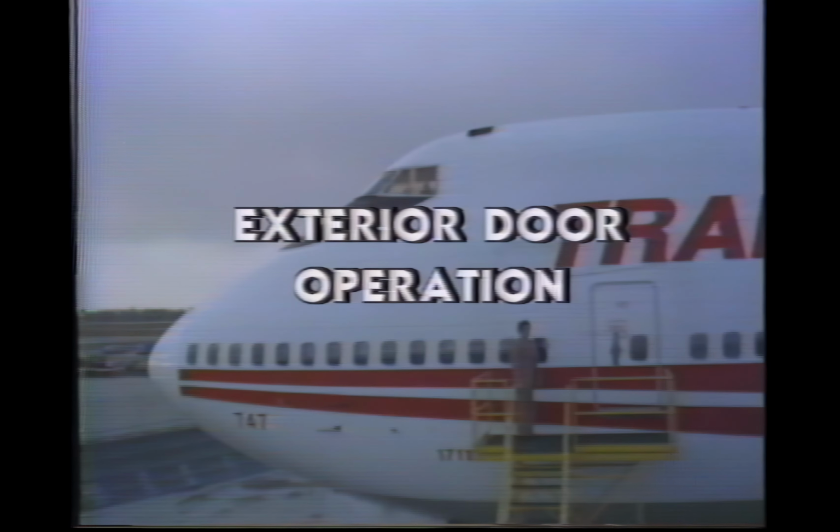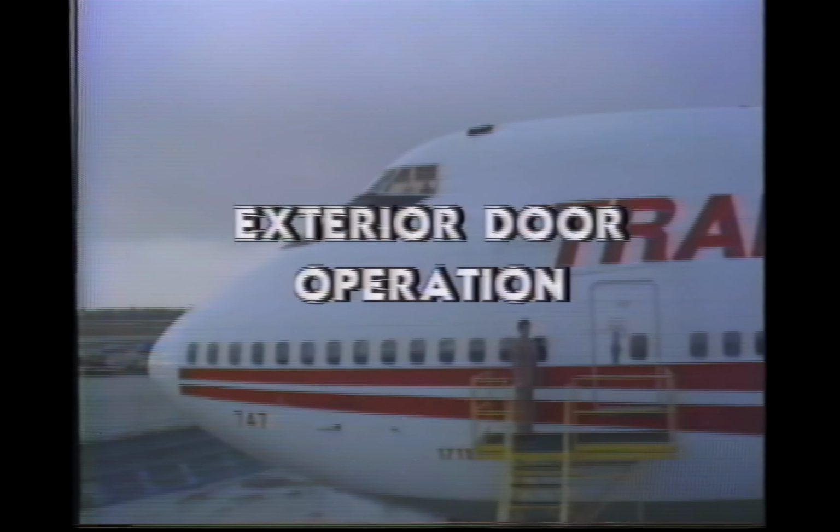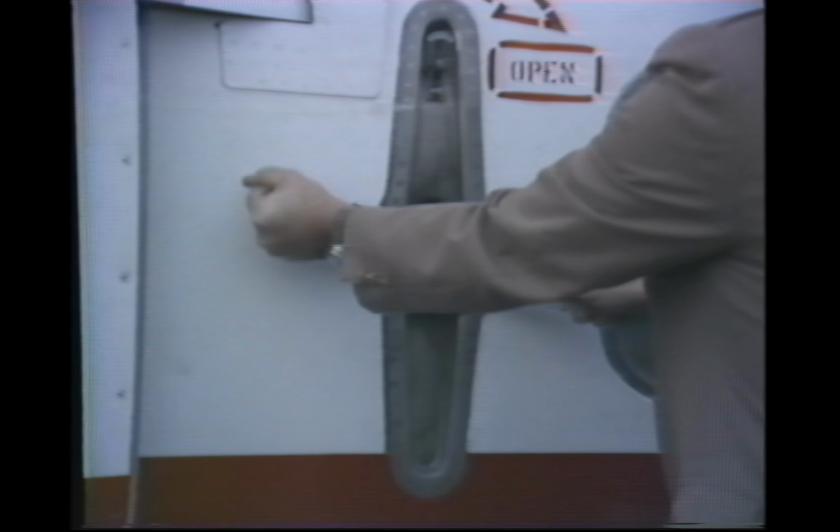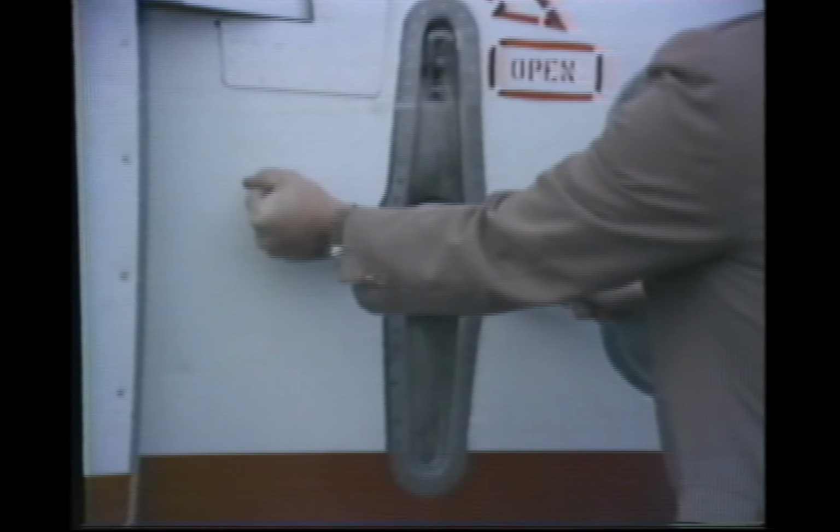To open any of the main cabin doors from the outside, push inward on the latch to release the handles. Pull out on the handles to the fully extended position. This deactivates the door emergency functions. Rotate the handle approximately 90 degrees and observe the lower edge of the door. If the slide raft girt is visible, do not open the door or slide raft deployment may occur. If the slide raft girt is not visible, rotate the handles another 90 degrees and restow the handles. The door can now be pulled to the open position.